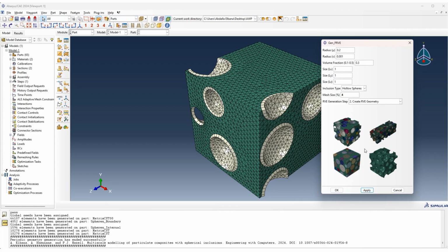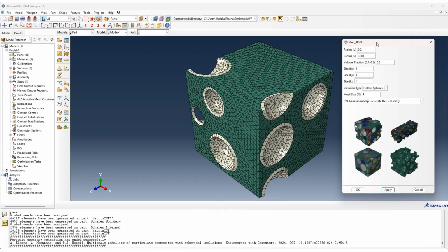If you don't want to proceed with a periodic mesh and periodic boundary conditions, you can stop here and apply ordinary kinematic uniform boundary conditions. Else, continue to the next step.